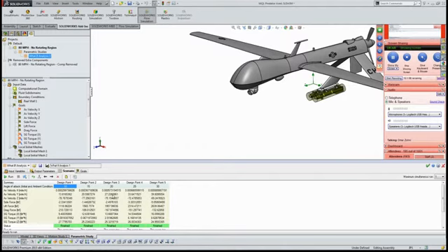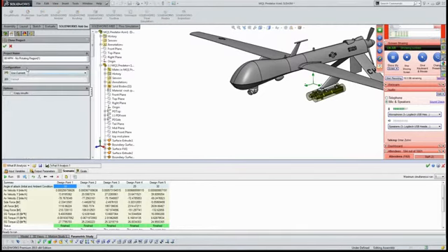And then again, a really nice thing about flow simulation is if I've got it set up for one of my configurations, here's my flow configuration, I can just right-click and say clone, and it's going to tell me, okay, what configuration do you want to clone it to? So if you have multiple configurations, you can create a master flow configuration and then copy that flow configuration, all the setup, meshing, and post-processing, into all of your other configurations.